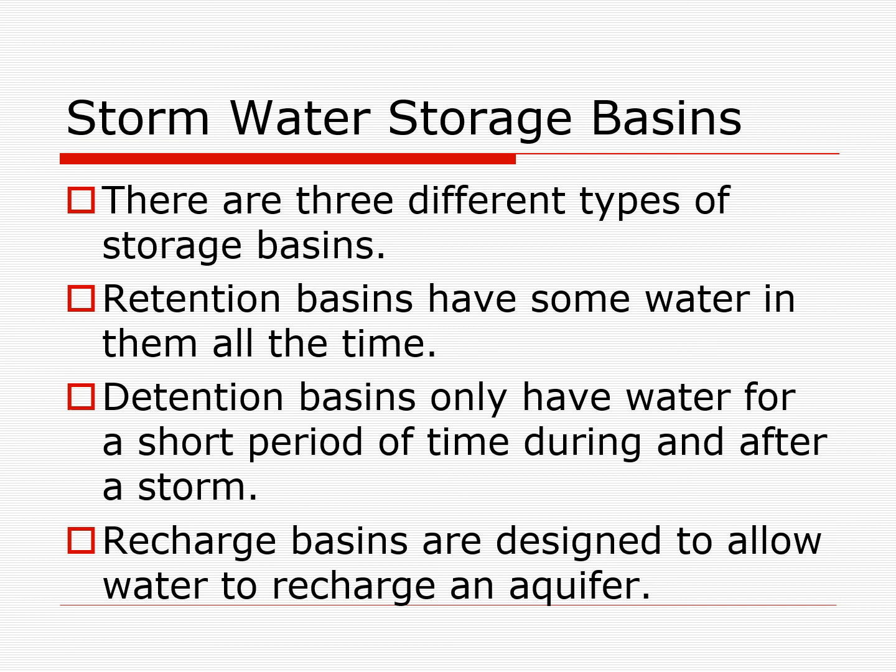And what these basins have is an outlet that is a metered outlet that allows a certain amount of water out of that basin at a time. So in that case, they were using it as also a feature of the property. There was actually a gazebo and picnic tables around that retention basin, but it also acted for stormwater.